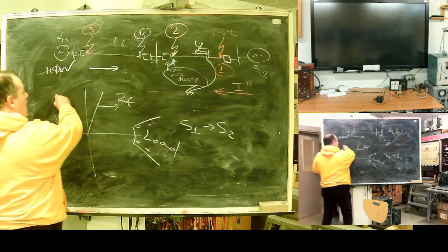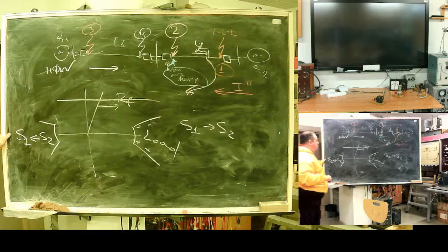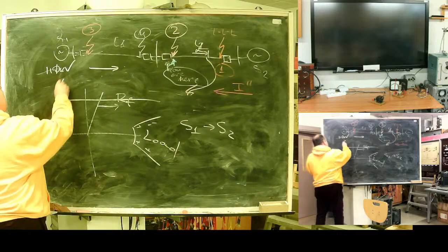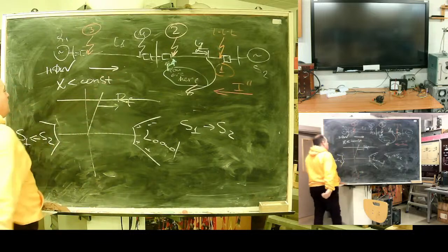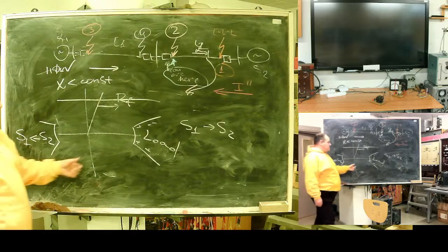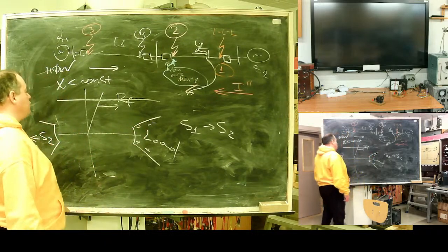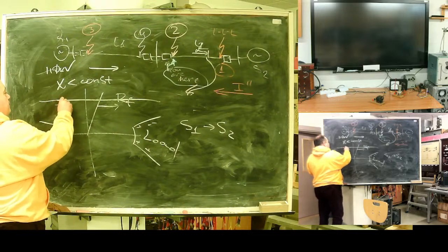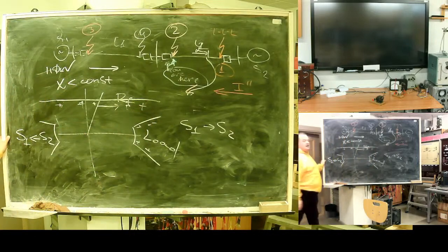In theory, one of the old theoretical objects is the so-called minimal reactance relay. A relay which operates if X, reactive resistance, is below a threshold. Such a relay is fine, until you understand that it will trip falsely from load regimes. I need to separate from load regimes, I need a right border.